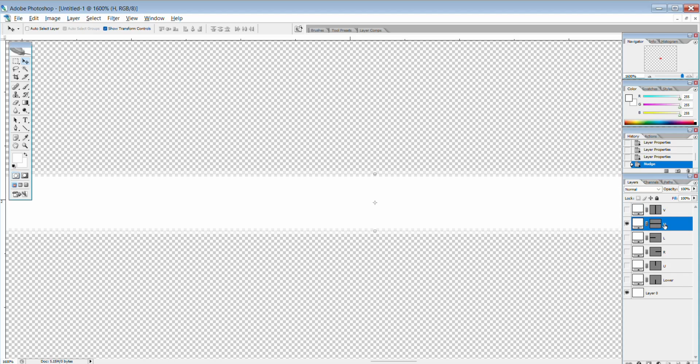Let's go here to the horizontal. And again, if I click on the layer first and click in this, you will notice it has now brought up the actual grid lines. And when I look at the placement by using the Control up and down keys, you can tell that this is now perfectly aligned on that 2-inch mark.